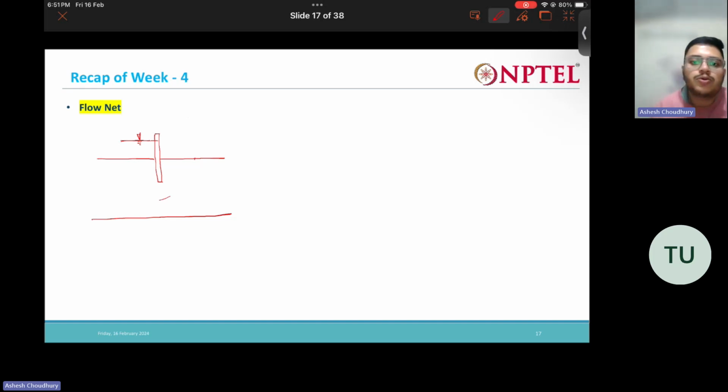How are we going to do it? One easy way is to draw everything to scale and then construct the flow lines. There are various software packages available which help in the construction of flow nets. If we construct the flow net, it gives us a means to calculate the amount of flow, or the amount of seepage of water, that is going to occur.